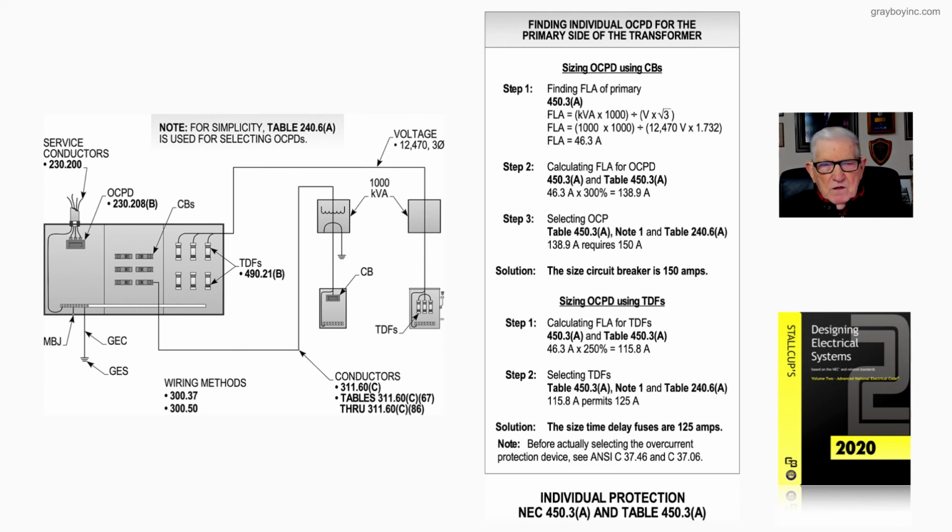But now notice, if you really wanted to size these fuses in accordance with standards that would list such devices based upon the system being over 1,000 volts, use ANSI C37.46, and you can pick up these standard protective devices for systems rated over 1,000 volts.